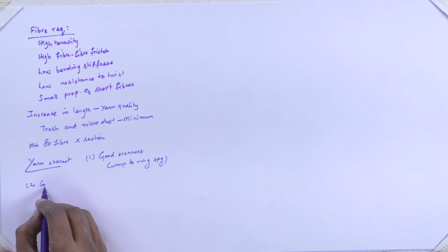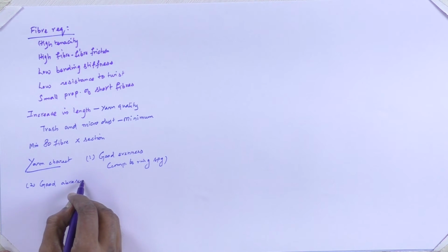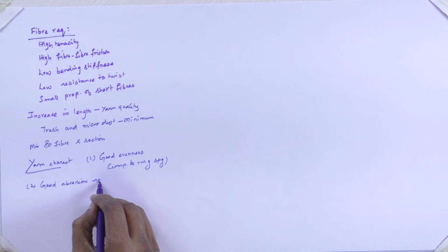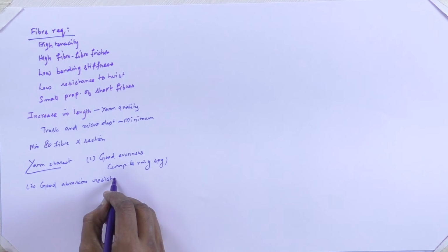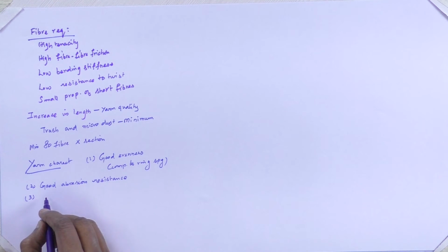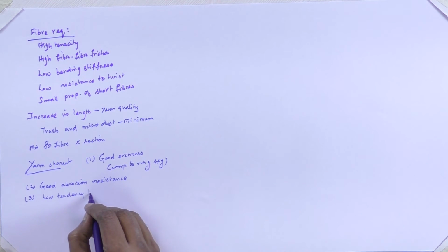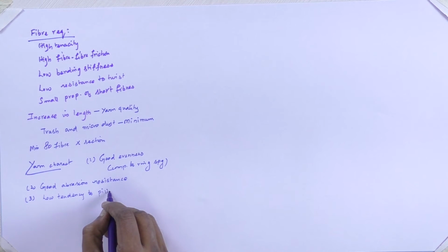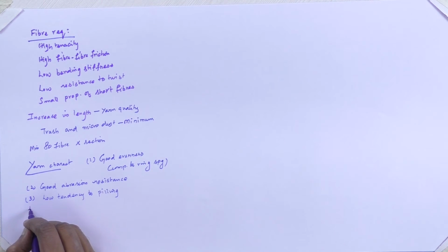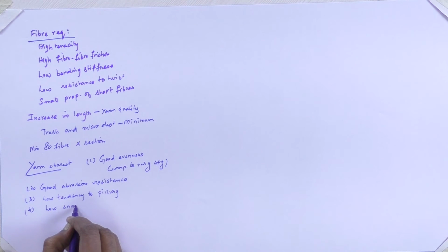Then good abrasion resistance, because of the presence of wrapper fibers, the abrasion resistance of the yarn is quite good. Then low tendency to pilling, again because of the wrapper fibers. Then fourth one, low snarling tendency.